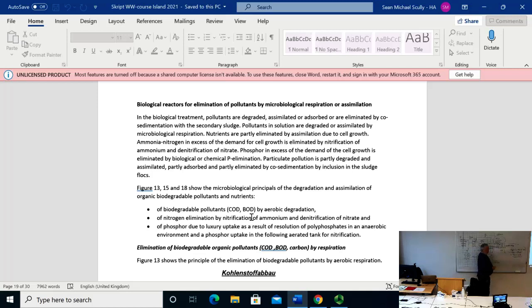And when we have this nutrient requirement, the COD ratio of biomass is about 1.4. So if you divide the 40 by 1.4, you end up with 28 grams of volatile suspended solids. If you assume 70% of ignition loss, you end up with 40 grams of total suspended solids in form of cell growth.